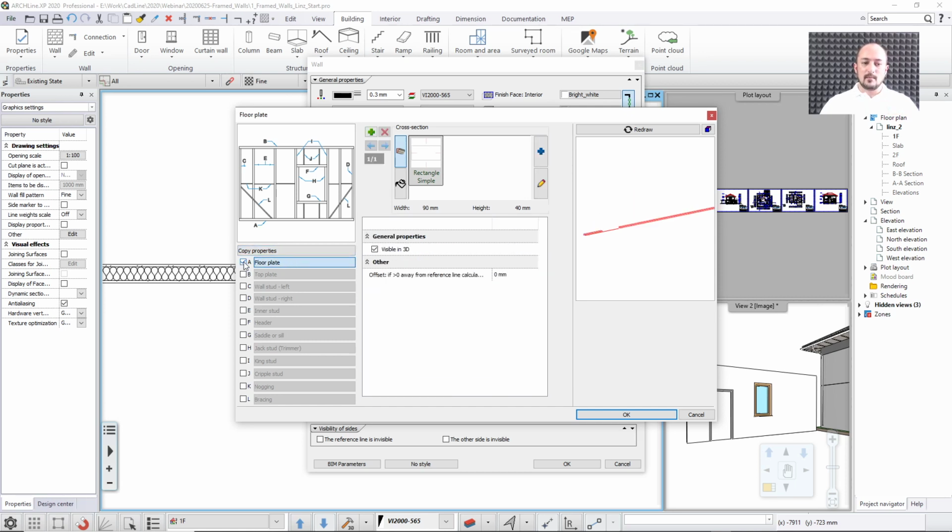Now if I just enable that and then I switch to that page, these are all the pages that you can design, then you have the option to change the cross section individually. You don't have to use all the same cross sections everywhere. You can change them according to their purpose, and you can even just use an offset. Usually what you can do with the structure is, at least you can set up the cross section, you can set up a material if that differs from the general settings. You can turn on or off the visibility, and you can also set up an offset. I will talk about that later.